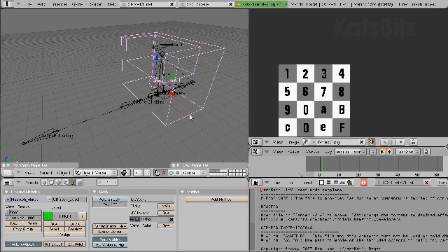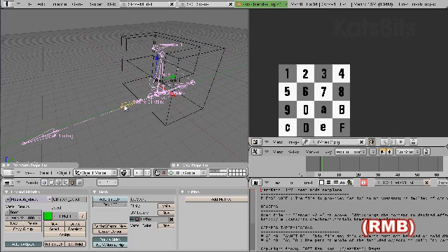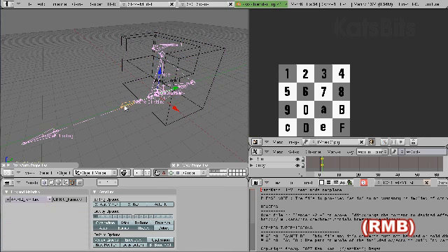The final step before exporting is twofold. We need to tessellate the mesh, which converts it from quads, polygons into individual triangles. We also then need to assign an action, an animation action, to the armature. So with that selected, let's do that first. We need to create an animation action for the armature.